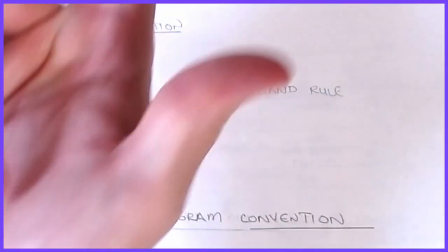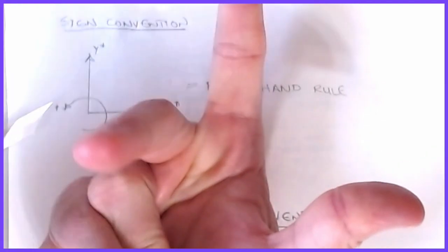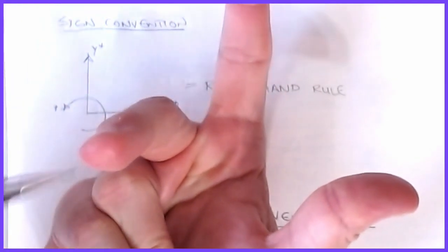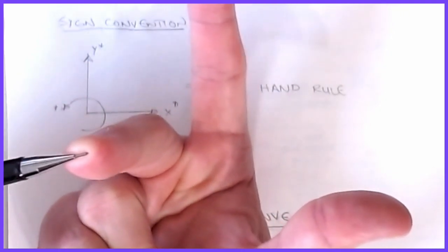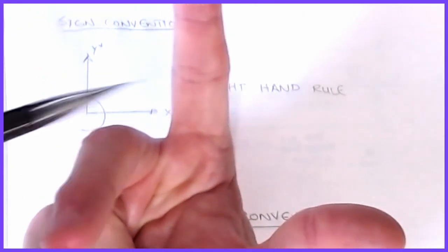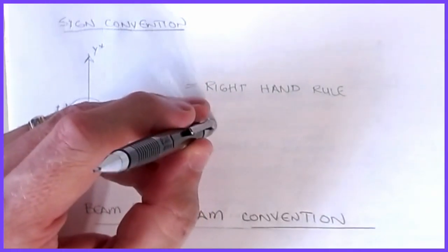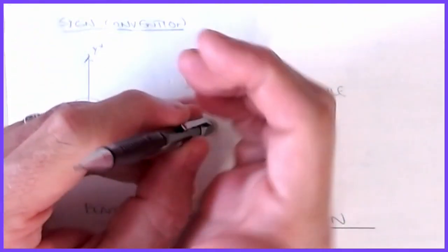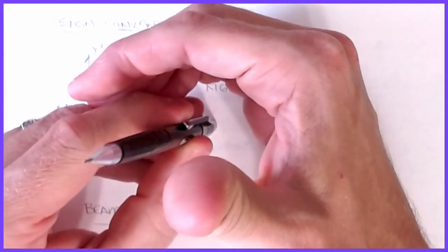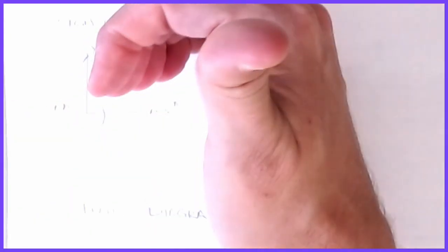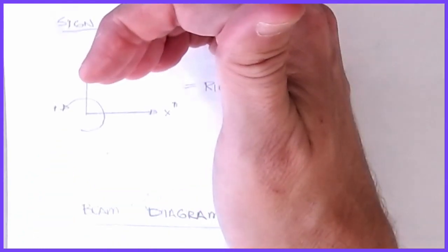If you remember, it's the old right-hand rule that the thumb is x, the forefinger is y, and then the finger that's sticking up perpendicular is the rotational axis. And if you remember that there are lots of right-hand rules that came out of statics, this follows that sign convention. So these two match the right hand. This is my right hand. And then this one that is acting up, if I show this as the axis in the direction of that middle finger, the right-hand rule wraps around this direction with my thumb pointing toward the positive end. I know this is really confusing if you haven't seen it before, but if you notice that direction of my hand curling matches the direction of this arrow, that's the right-hand rule. It's actually two right-hand rules put together.